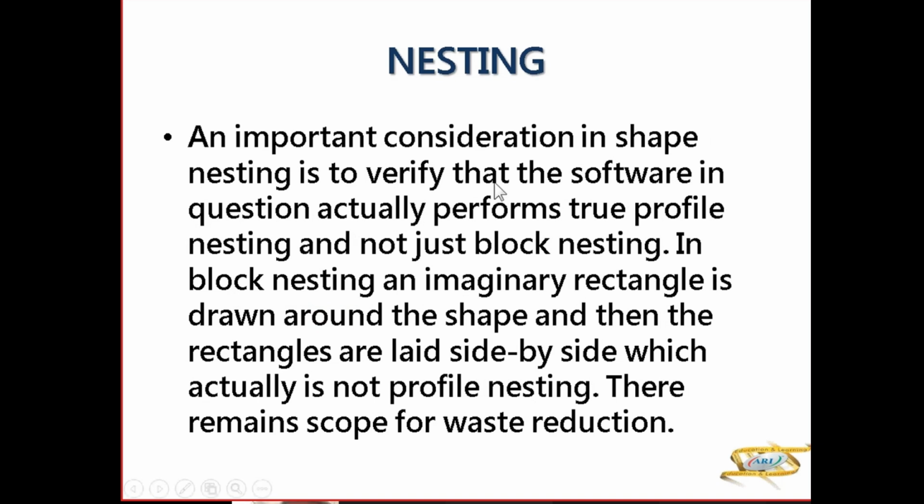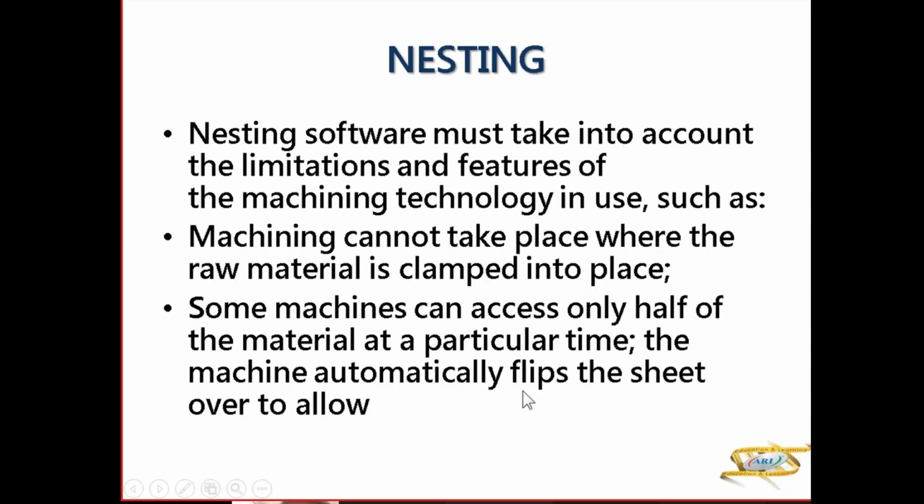So here basically it verifies that the software is actually performing true profile nesting and not block nesting. Block nesting is an imaginary rectangle which is drawn around your shape and then rectangles are laid side by side. Profile nesting basically आपका odd shapes का है. So here you are reducing your wastage.